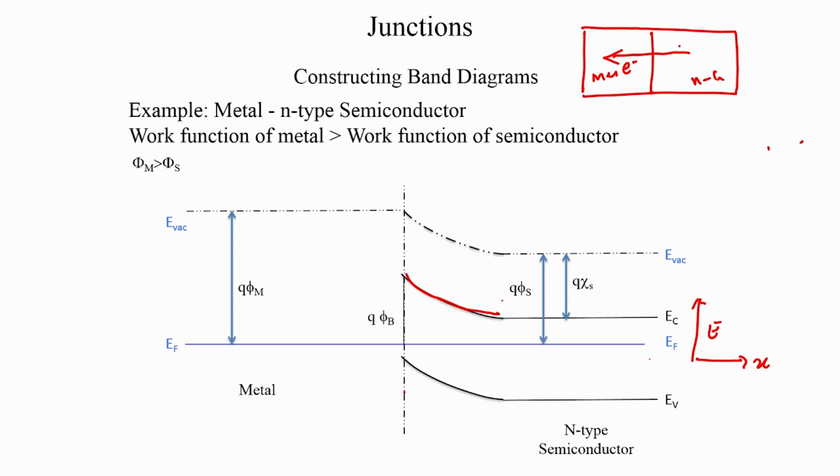Essentially what this means is that the region located at lower energies has a higher potential as compared to the regions located at higher energies. So, if there is a metal and there is a Fermi level here, and I increase the potential of the metal, I increase the voltage, the Fermi level will start moving downward.